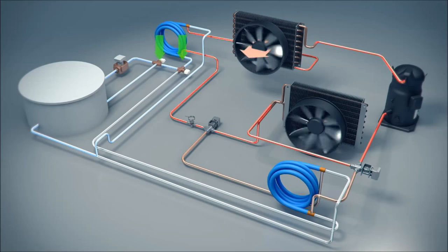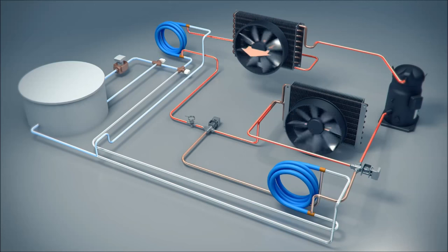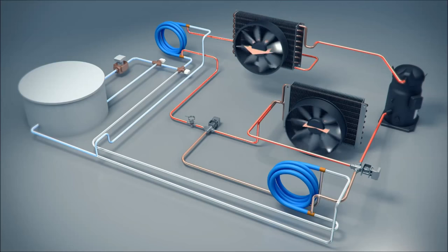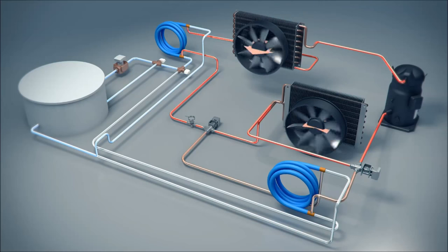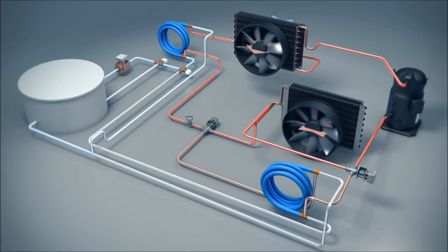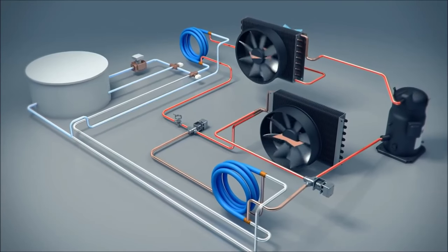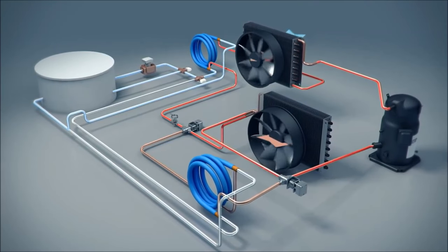of hydronic control valves. The valves function to provide both volume control and loop selection. Exiting the valves, which are managed by the System Logic Control Center, the glycol re-enters the AC Companion heat exchanger. The aforementioned process simulates an artificial environment at the condensing coil found in the standard AC refrigeration cycle, consistent with an ambient temperature of approximately 60 degrees. This allows the air conditioner to always perform at its optimum efficiency.